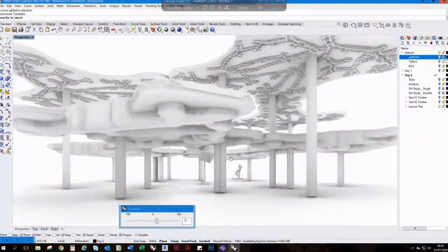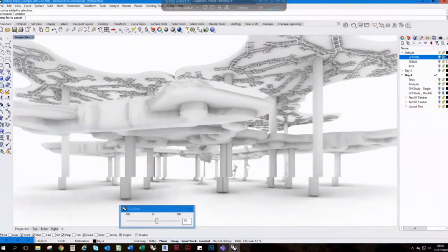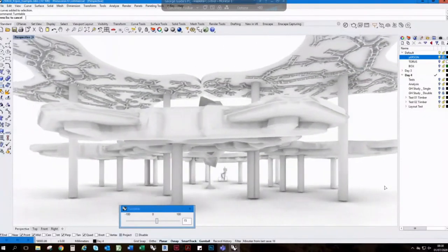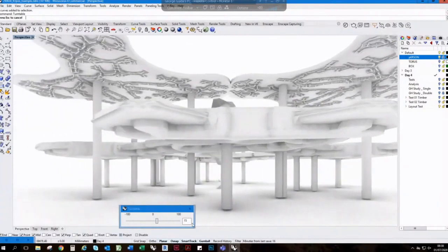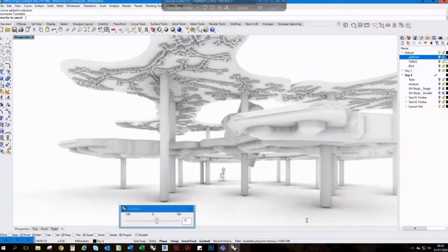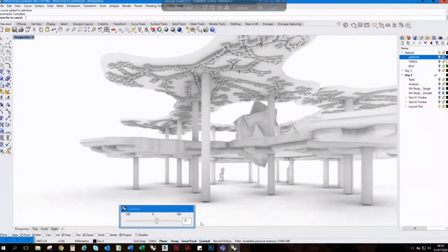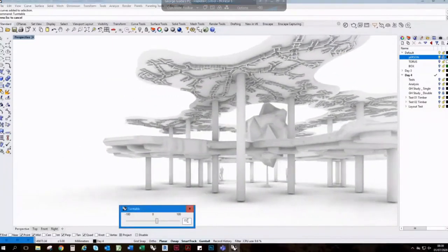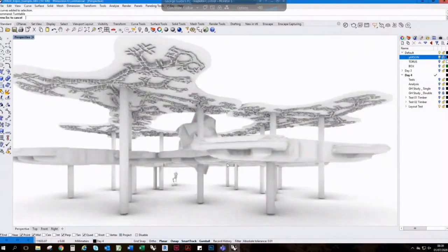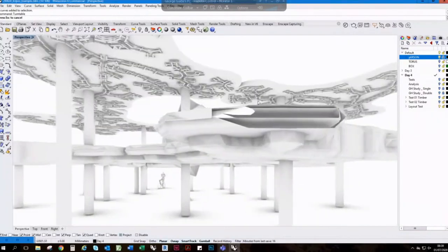And the pattern generated, because it will be strongly influenced by point forces. We hope here that if we keep the columns continuous, we can basically reuse our analysis of the first floor and stack it on the third floor, and then just by copy pasting the elements. I think that's more our practical approach for this week, because with unlimited time, you can of course simulate every unique configuration and every floor.